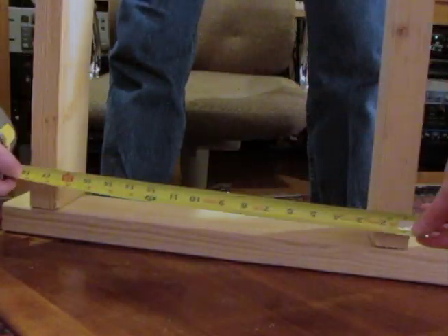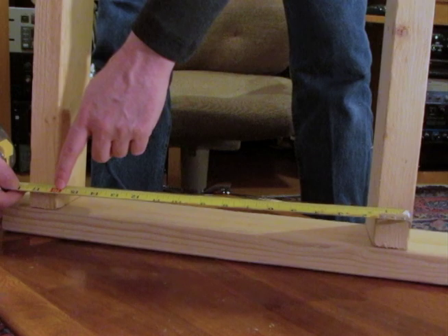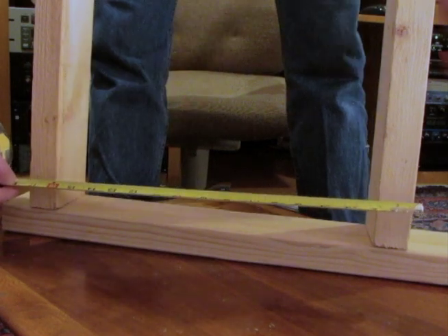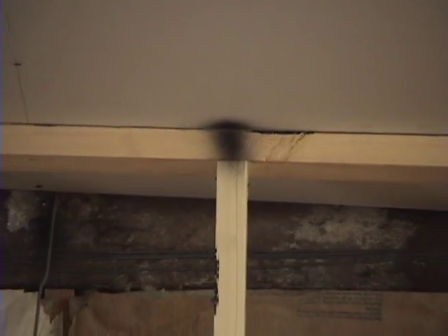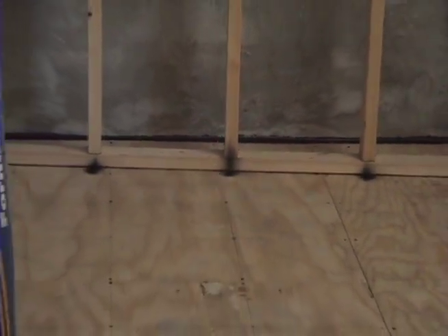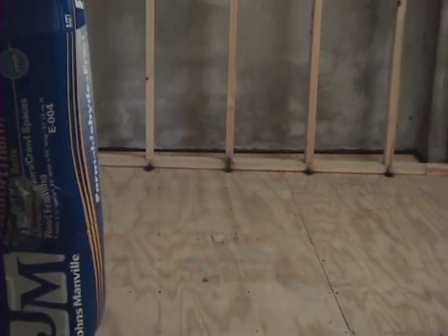Then place a stud every 16 inches on center, which means that if you measure from the right side of one stud out 16 inches, then the right side of the next stud will be lined up on that mark. After your studs are installed, go around and mark on the ceiling and on the floor where each stud is to make it easy to hit when you're installing the drywall. We use black spray paint for this.